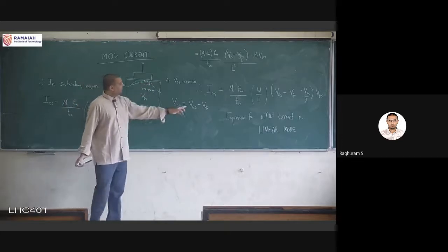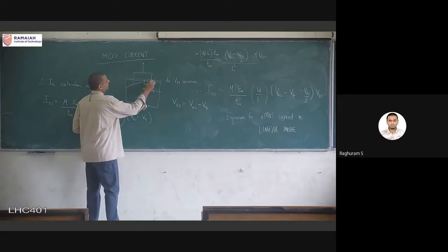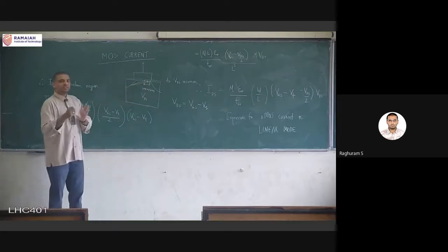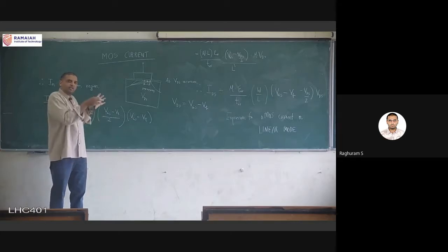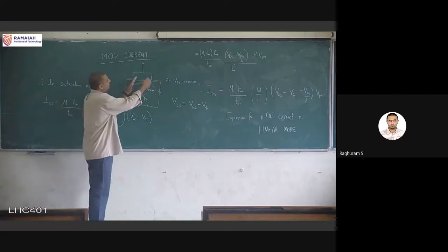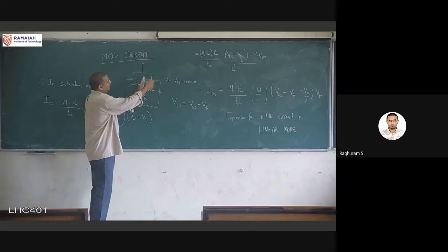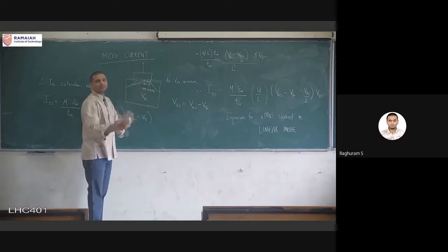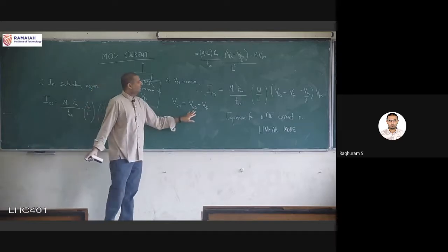That is why the boundary condition, okay, where exactly pinch off occurs at this point, at this condition, VGS minus VT equal to VDS. Beyond that, whatever VDS you apply, only VGS minus VT is responsible for the movement of the charges in the channel region. The remaining part of the VDS keeps applying across the region where pinch off has happened. It does not contribute much to the current. So that is why we don't change VDS anymore.